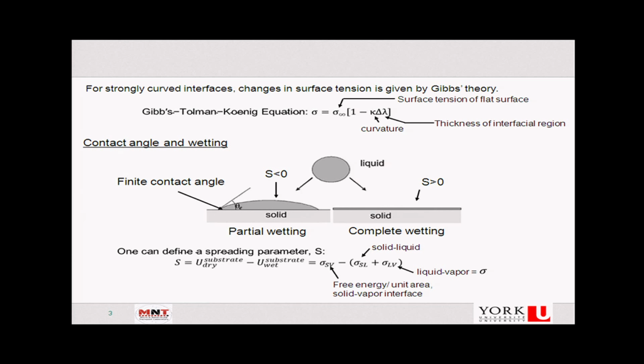So these two differences really dictate whether you will have complete wetting. In the case of glass, this value is greater than 0, so you have complete wetting. Whereas in plastic there is partial wetting. You still have drops wetting only a part of the plastic, because that value is less than 0.